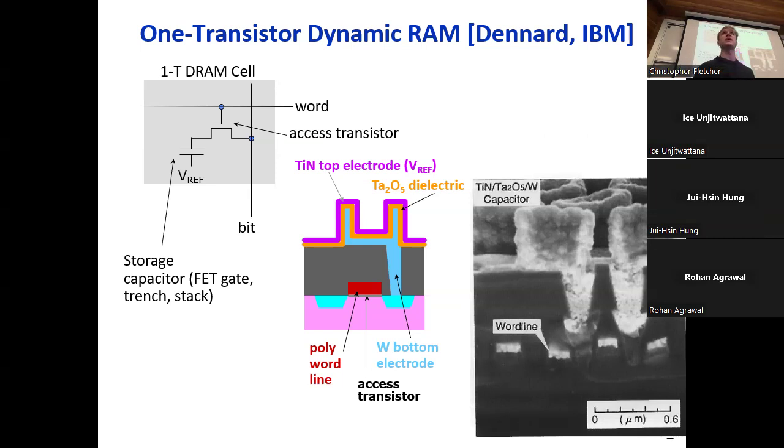We're going to use DRAM to get the concepts down, and then we're going to do a quick compare and contrast between DRAM and SRAM. The spoiler alert is that if you understand the differences between a DRAM cell and an SRAM cell, how these cells are organized into larger memories looks similar from a 30,000-foot view.